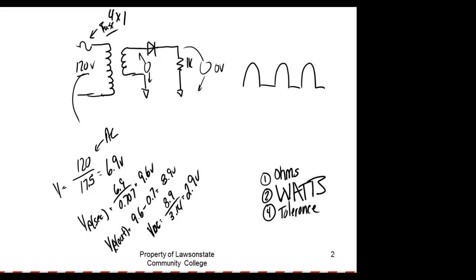You understand? Now I know right here, on that secondary of the transformer, am I supposed to measure DC or AC? I'm supposed to measure AC. On the transformer, we're supposed to measure AC. So I'm going to put my meter right here on AC and measure the secondary of the transformer. Here's the secondary, and it's measuring 6.8. I'm sorry, 7.2. You know it's a little high, right?